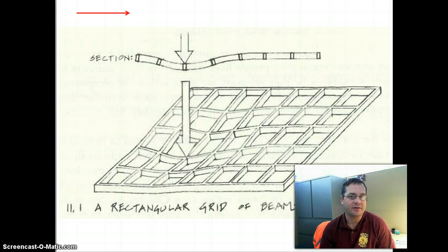And the classic examples are structural steel. That's highly isotropic, very strong in tension, very strong in compression, and reinforced concrete, which we've discussed a lot in this course. And remember that reinforced concrete is a composite between concrete, which is the compressive member of the composite, and reinforcing rebar or tensioning tendons, which are the tensile parts of the structure. So those came together, and with steel structures or with reinforced concrete structures, we're able to span great distances without taking on that arched shape.